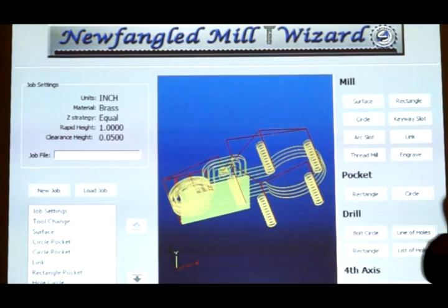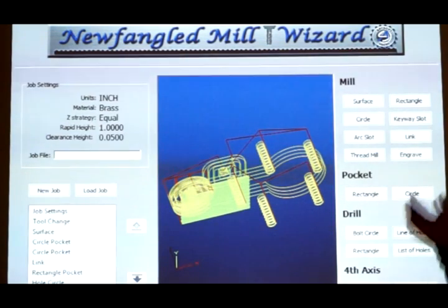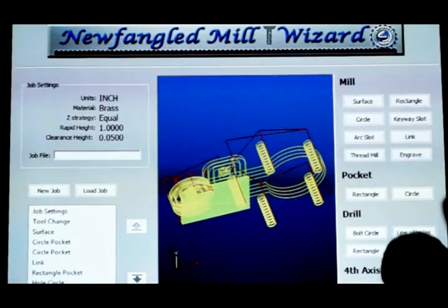Anyway, we can do a line of holes with the same drilling cycles. I can do a rectangle where I drill the outer perimeter or I drill the entire matrix with a click. It says outside or fill in the perimeter. And I can do a list of holes. A list opens a spreadsheet of XY values and has an import button. So if you've used an Excel spreadsheet to create a list of holes that you want to drill, let me see if it'll come up here, just so you see what happens.